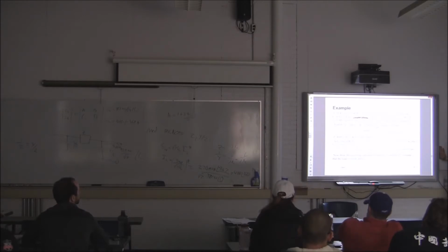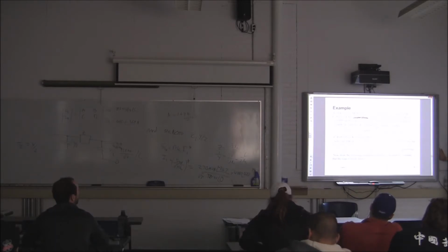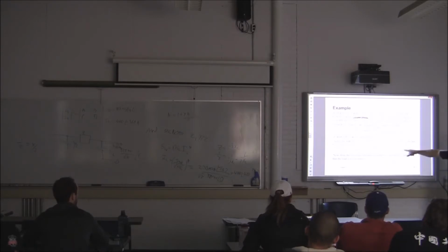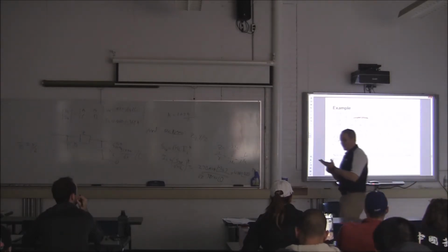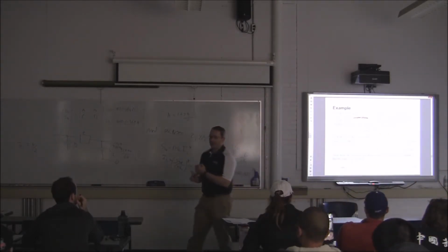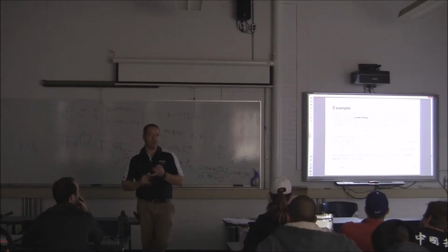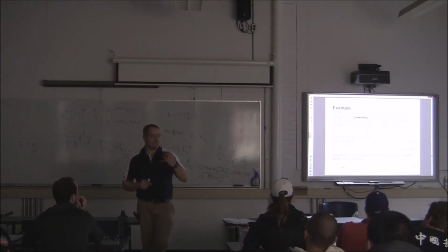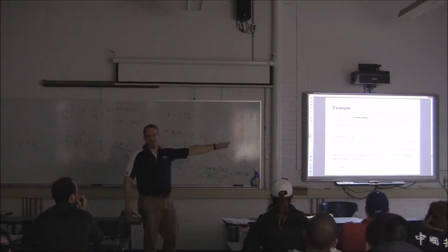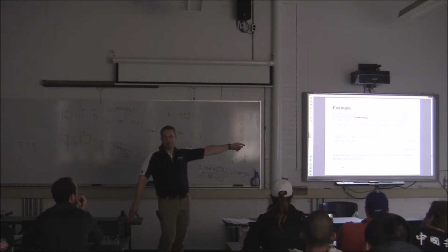So if I invert that, that's going to be a really large number, right? So there's not a lot of current and not a lot of reactive power going in or coming out of those capacitors. But this is where MATLAB is really nice and useful to work with. Or if you all are using your TIs to do that, I would encourage you to set up an ABCD matrix, and then let it be equal to a Z and a Y term, and then just solve for your Z and your Y each time, and then update your ABCDs. Because these get to be really crazy small, and it's hard to write them. But if you store it in your calculator, it's not so bad.